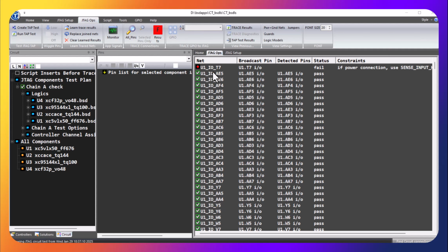For example, I just flipped one of the switches on the board, and that changed the configuration. So we have a failure at this pin T7, which, since we have the schematic, we're not using the net list, but we can see that this pin is indeed connected to the switch, and we've changed the connectivity. So you do get diagnostics. So even with just a BSDL-based application, you will get a test and diagnostic. So it's a pretty powerful technique to find and debug boards, prototype boards, or whatever you have.